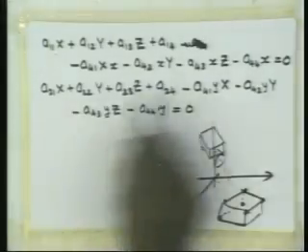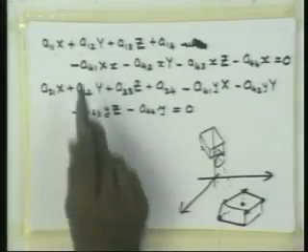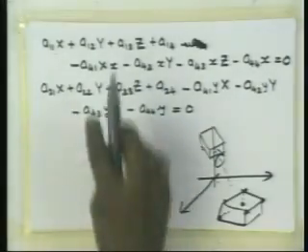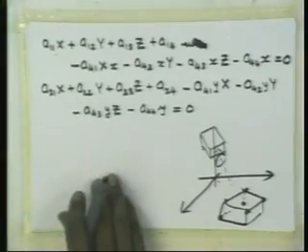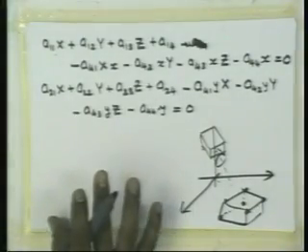I can substitute them in these 2 equations. So 6 points times 2 equations, 12 equations I will get, and I have 12 unknowns. It is a linear problem of simultaneous equations. All right, so this is how cameras are generally calibrated. It could be done periodically, or once in the beginning of the task and then used the next time.